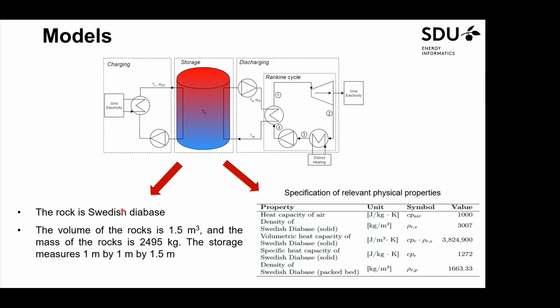The question was, what is the simulation timing? Could you repeat the question? I mean, what's your sampling time and your prediction horizon time for your MPC? The prediction horizon was 24 hours. The control horizon is 15 minutes, and in our scenarios we simulated 7 days to demonstrate. Okay, thank you.